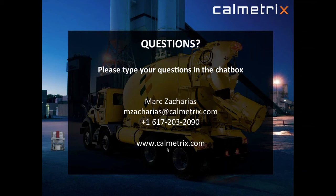You would have to put your mix in and establish this correlation, and then once you have it, you can use it. Yeah, I'm assuming, Mark, that that correlation would be a function of the mix design. That's right. The mix design, of course, and the type of impeller you use. As I said, we have the attritor impeller, but you could use other impellers. The size of the vessel, the size of the mix, and it also depends on your shear rate. But if you keep everything else constant, then you can make a correlation, and you could use this as an approximate slump meter.